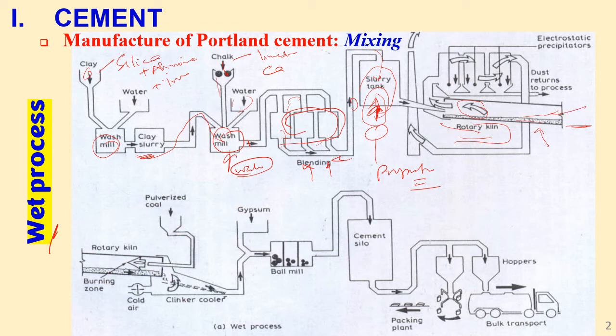And from the other side, hot air, whether from power coal, oil, or natural gas, is blown, a hot air blast, from the lower head of the kiln. This is the lower head, this is the upper head. And you see, as it rises up, it meets the slurry which is going downwards. At the bottom head here, the temperature reaches as high as 1450 degrees.